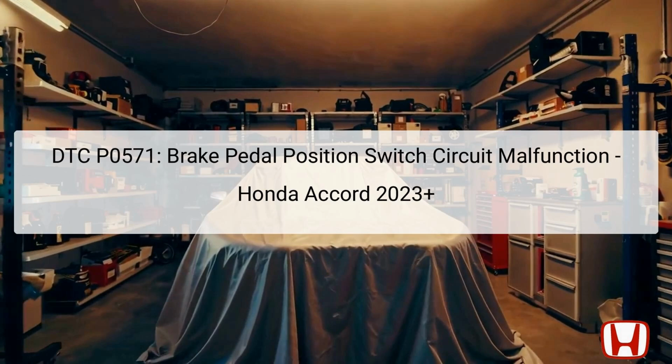DTC P0571 refers to a malfunction in the brake pedal position switch circuit in the Honda Accord models of 2023 and above. This error occurs when the brake pedal position signal does not correspond with the actual brake pedal operation during certain driving conditions. The Powertrain Control Module, PCM, monitors the brake pedal position to ensure that it functions optimally. If it detects any inconsistencies, it logs this code and triggers warning systems.